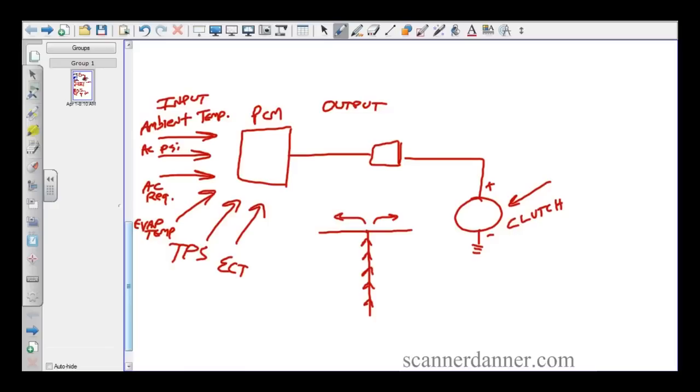A scan tool bidirectional test is where we want to possibly start. It's not where you're going to start. I'm not saying you must start here. I'm saying use the tool that's in front of you to its fullest and know that what the tool does can help you here. If I take this car that the clutch will not turn on, and I'm jumping ahead,